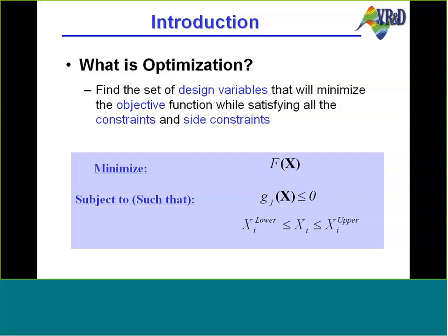In structural optimization, it means that the design variables are going to control the layout of the structure. It can be things like dimensions or sizes that define how we can build some particular structure. The objective function and constraints are going to come from responses from a structural analysis. And they could include anything from mass or volume to responses like stress, displacement, eigenvalue.